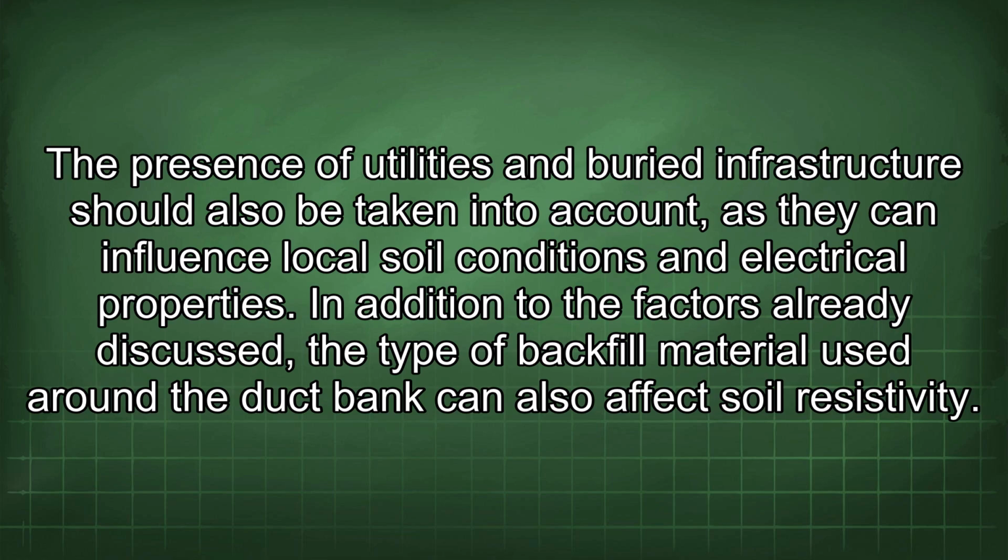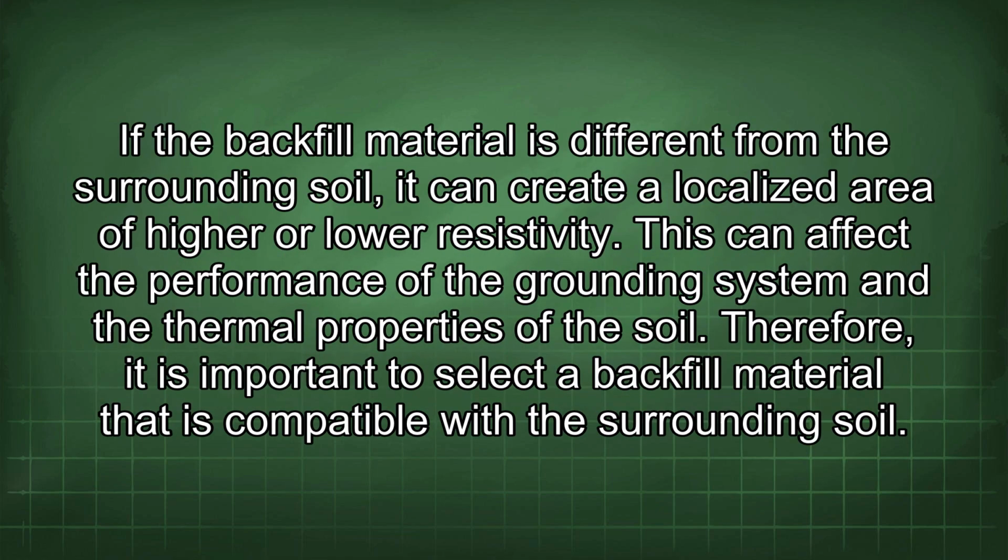In addition to the factors already discussed, the type of backfill material used around the duct bank can also affect soil resistivity. If the backfill material is different from the surrounding soil, it can create a localized area of higher or lower resistivity. This can affect the performance of the grounding system and the thermal properties of the soil. Therefore, it is important to select a backfill material that is compatible with the surrounding soil.